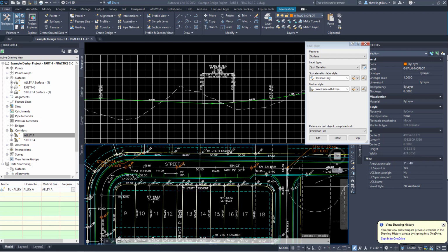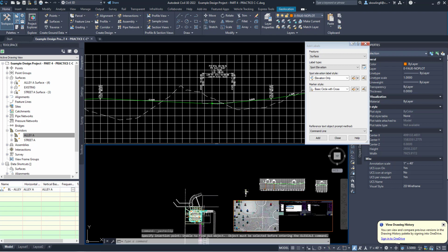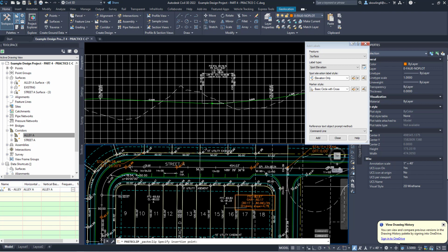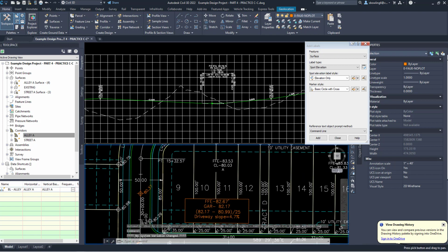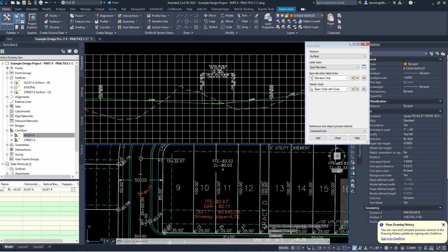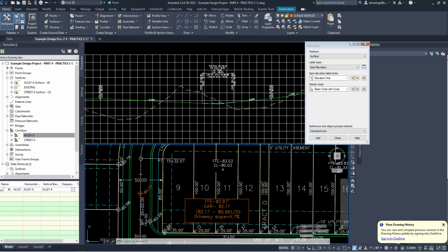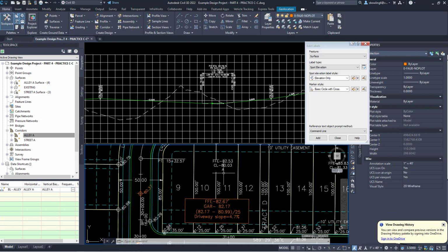Now, we would need to take a look at the driveway slope. Oops, that's not what I wanted to do. All right. Control copy. Let's see if I can get that to paste correctly over here. There we go. I did a piece of text over on a different drawing. I'm just going to do this simply. So let's say the garage, that's some bad math. That should be 82.53. Wow. So we go 82.53 because it's 2.5 feet higher than the center line.